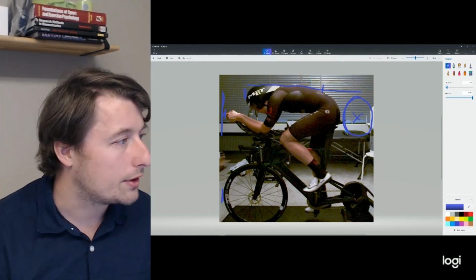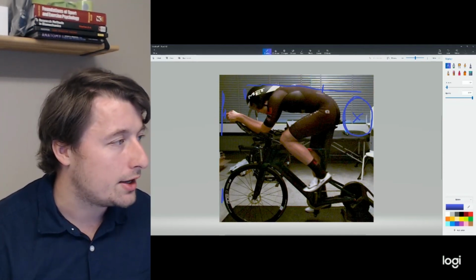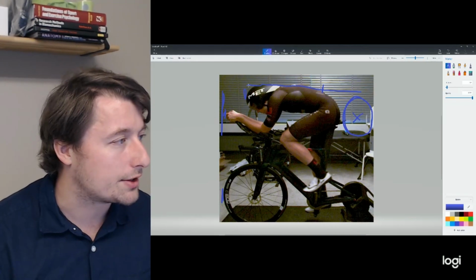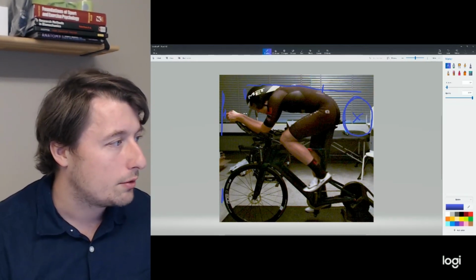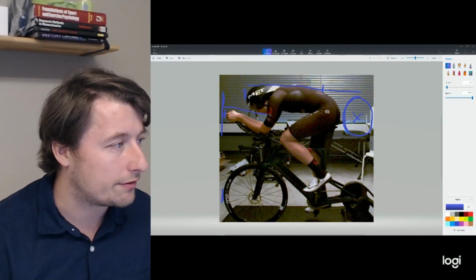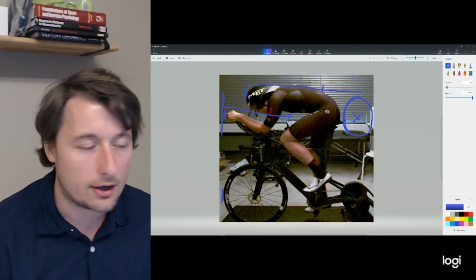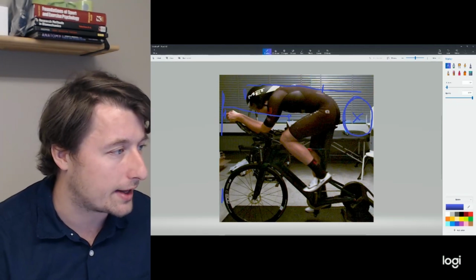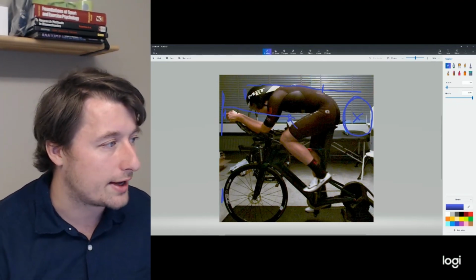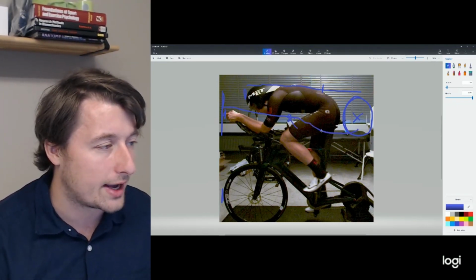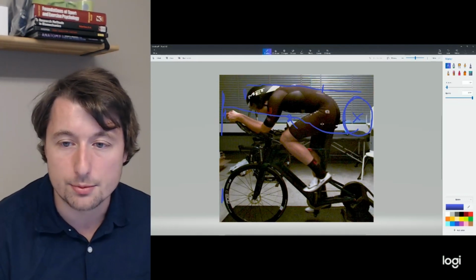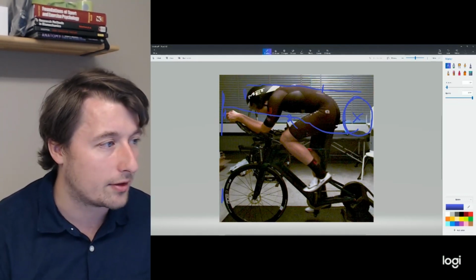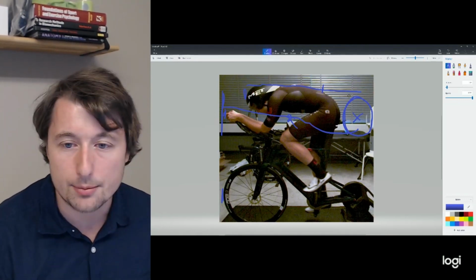So when we're thinking about a bike position, like I said, we ideally want a smooth line through the head into the shoulders. We want to reduce a lot of the airflow coming underneath this area of the position and catching under the torso, because that's already going to create quite a lot of turbulence as the legs move up into this position, and the air flows in and then has to bounce around the legs. So the flow coming off the back of the legs is going to be much, much more turbulent than off the back of the torso, for example.